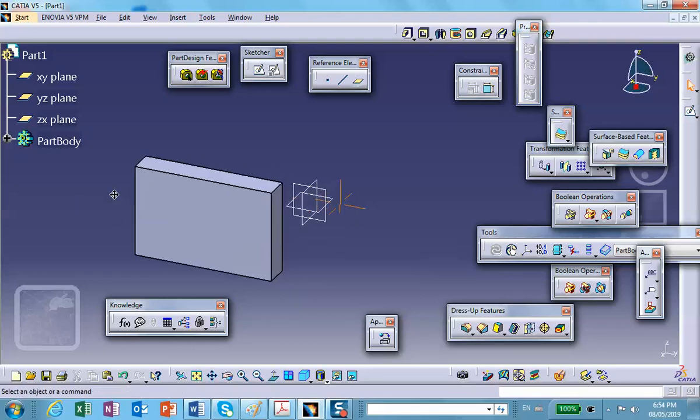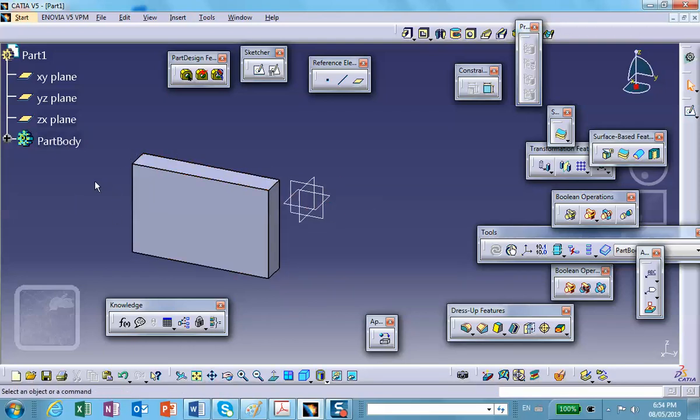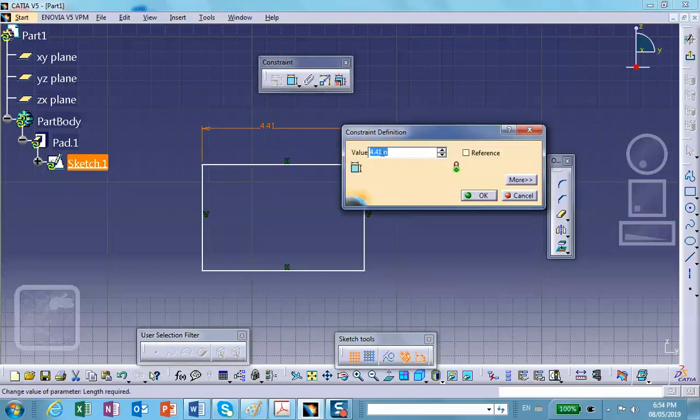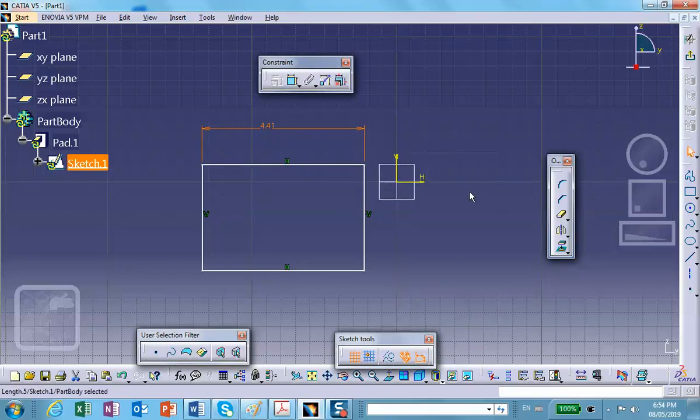Okay. Let me actually go to this sketch and put some dimensions here. Here's a dimension. Right now it is in inches. If you double click on it, it says inches. And by the same token, the angle, okay? The angle, we're never going to change it to radians, but it is possible. The angle, we use it always as degrees.